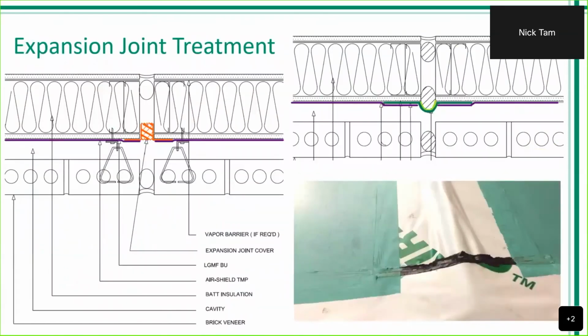For expansion joint treatments, it's not as simple as just striking it flush with an appropriate liquid filler. In some situations, we may have to have a specific joint filler or insert a Balca rod at that expansion joint, finishing off with a strip of flashing peel and stick, and then having the primary membrane treat the edges of it, and we have the full encapsulation and effective seal.